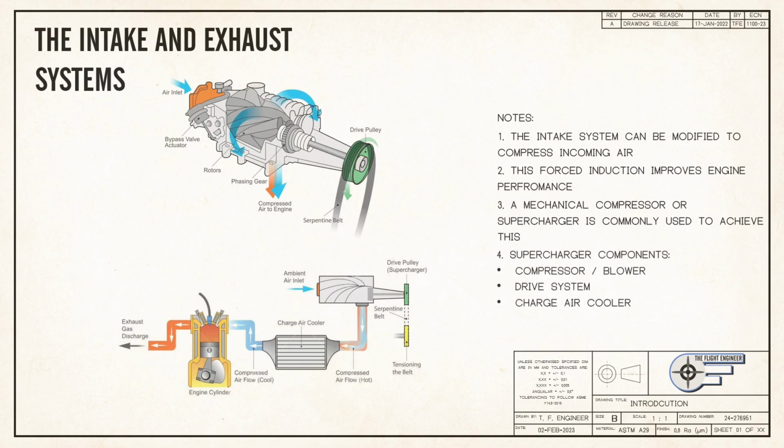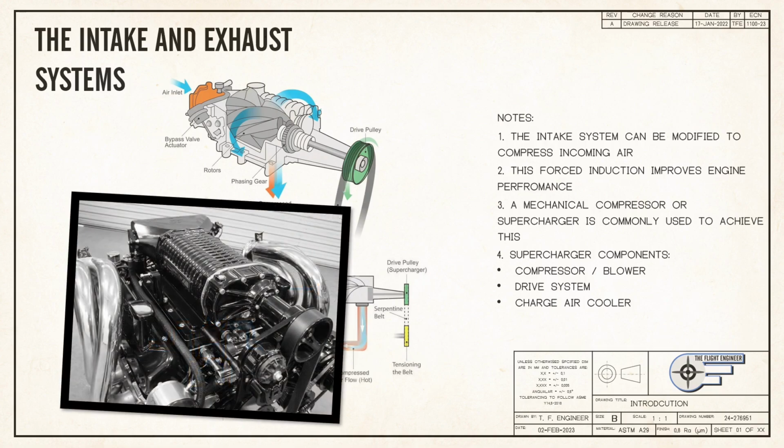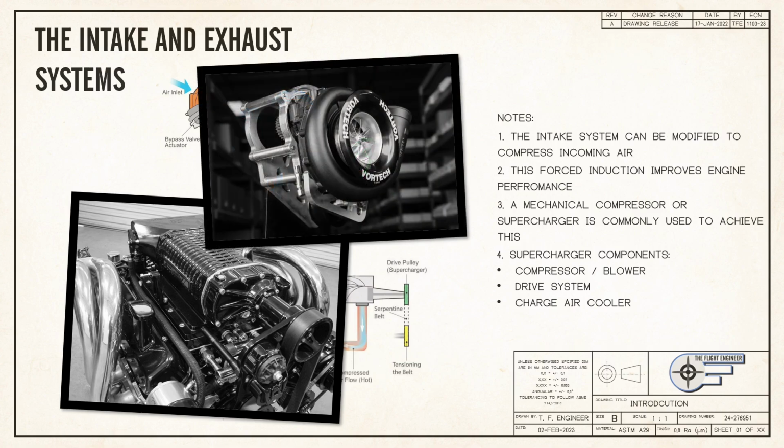The supercharging system centers around the compressor itself. There are two basic types of superchargers. Roots, or screw-style positive displacement units, provide a fixed amount of air per revolution. Meanwhile, dynamic compressors, like the centrifugal supercharger, compress incrementally more air the faster they operate.